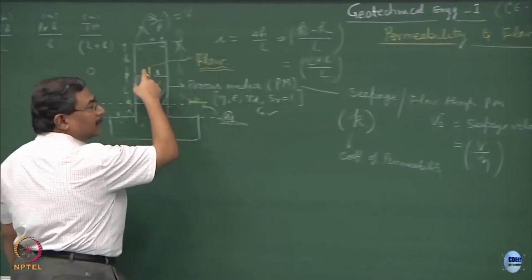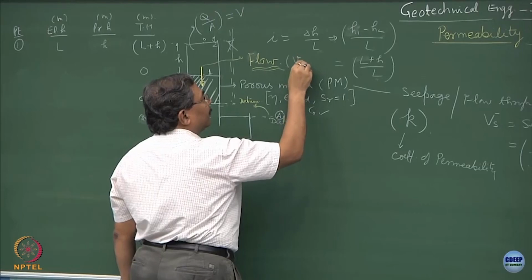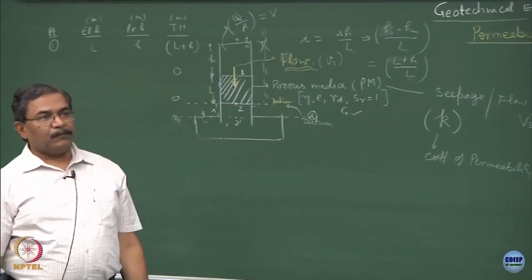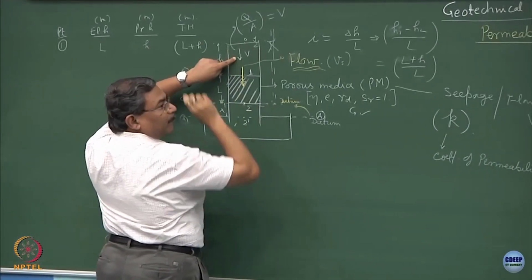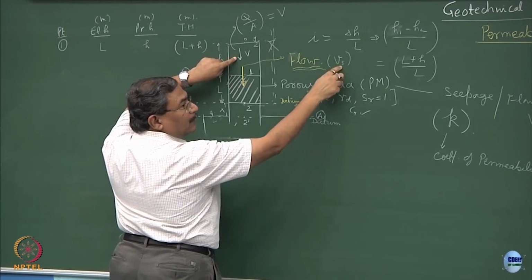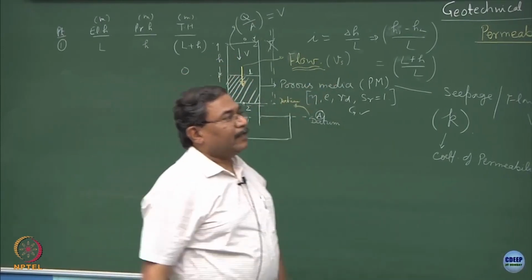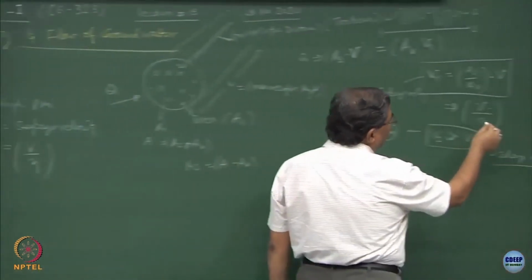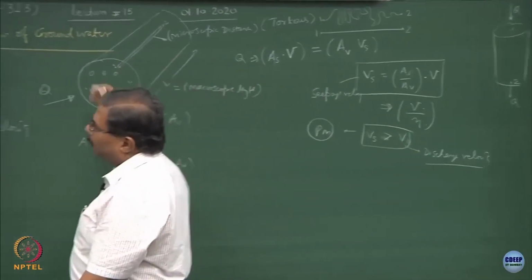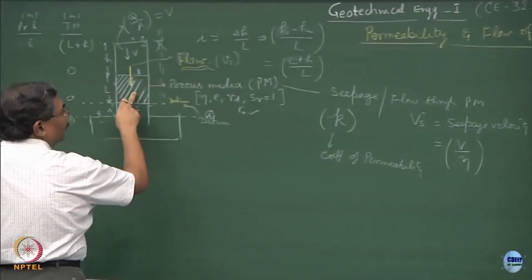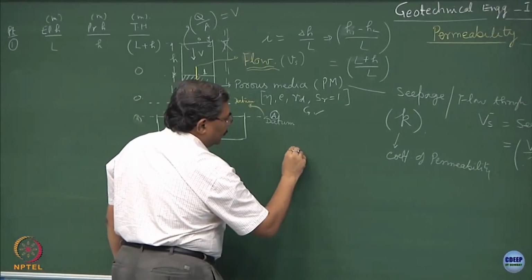So, when I say the flow has initiated because of the hydraulic gradient, there is going to be a velocity component Vs. So, V is known, capital V, if porosity is known, Vs is known, and you can show how Vs is changing with respect to V. Now, because of the virtue of this porosity, as I said, Vs is going to be more than capital V, the discharge. So, this is what we have to include over here. Is this part okay?